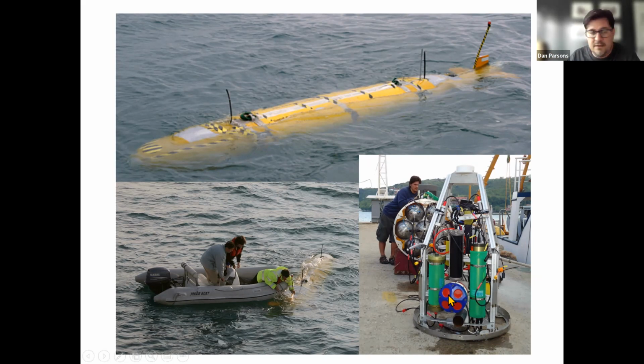It measures the velocity of the fluid using Doppler shift, the same way in which you can compute the speed of an ambulance based on the way in which the sound waves from the siren get compressed and then extended as it's coming towards or away from you. It uses the same principles here to measure flows. Now these are used lots in river systems to get discharges and flow velocities in rivers,